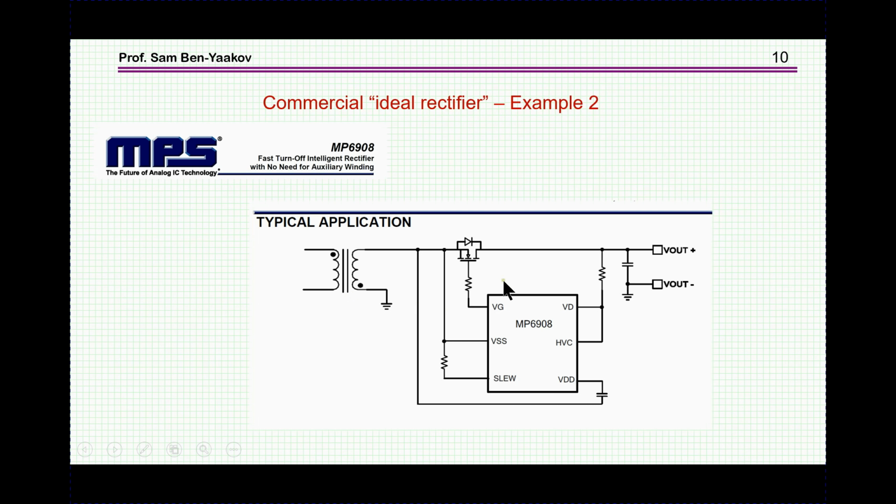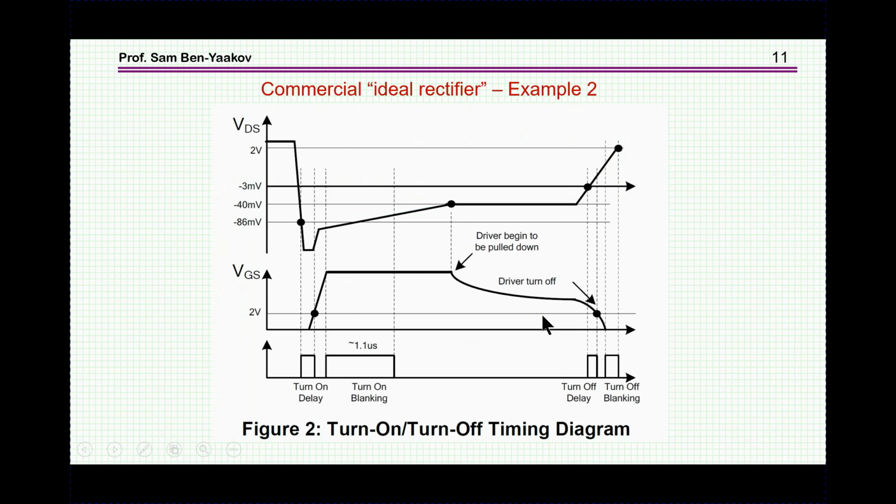Here is the transistor. This is the unit, again self-contained. There's no signal coming in. And again, the voltages are sensed, and then the transistor is turned on and off depending on the voltage across it. So here we see a sequence again in which the element is blocking. This is the VDS voltage is high, so the transistor, or the diode, is not conducting.